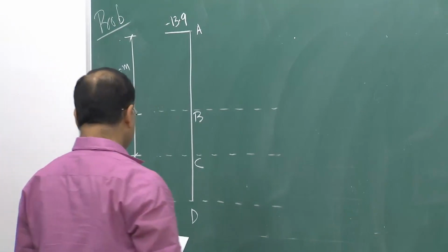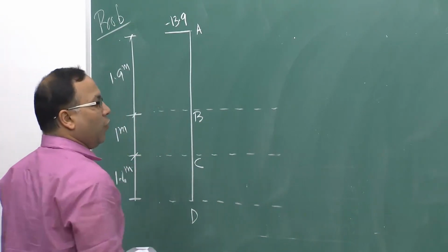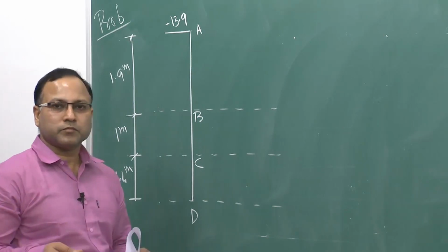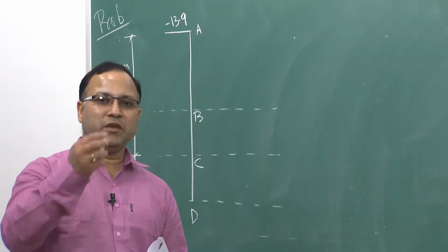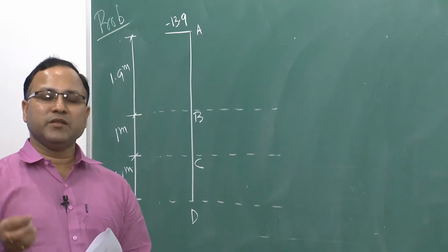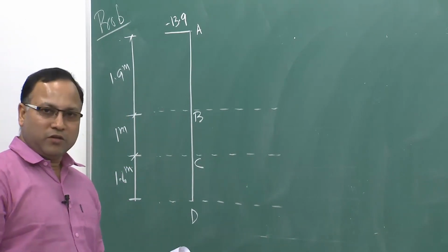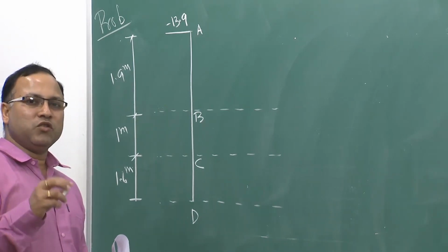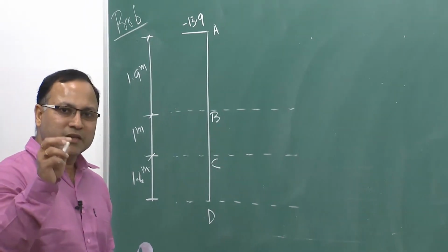Okay. Then where it is crossing over, where your pressure is becoming 0, active earth pressure is coming from negative side to positive side, where it is becoming 0 at z naught, right.